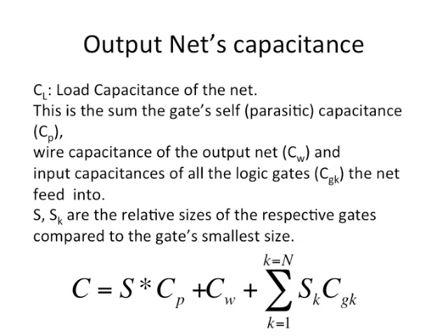Why would you scale it? Why would you size it up? For speed reasons. If you recall from the last semester's lectures on delay minimization, if you want to improve speed, you want to upsize the gates. So you might upsize this gate.